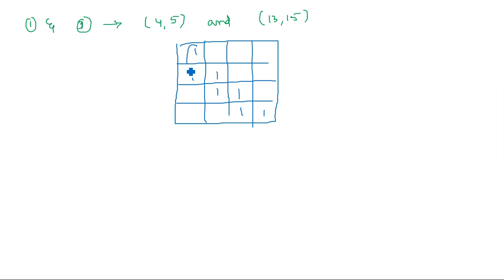See, you have like this. First, these two are already mapped. These two are already mapped as essential prime implicants. Now, I am saying map these two as one set and map these two as another set. This is one possible set. So that's why it is 1, 4 comma 5 and third, 13 comma 15. This is one set we can take along with these two. Okay, total how many? 4 minterms are derived from this K map.